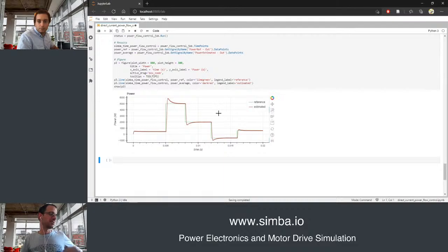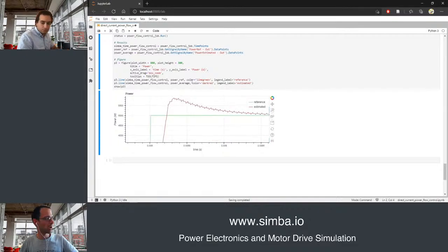So we can see that in steady state the behavior is okay, because it follows the reference. But on the other hand, this overshoot here can be a little bit annoying. So in this case, maybe it could be very useful or more convenient to design a controller with zero compensation. So maybe this will be shown in the next webinar or in the next part on LinkedIn.